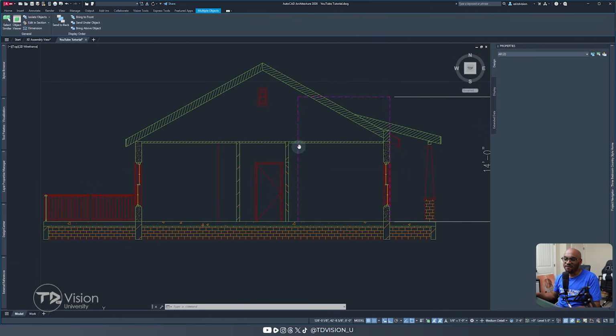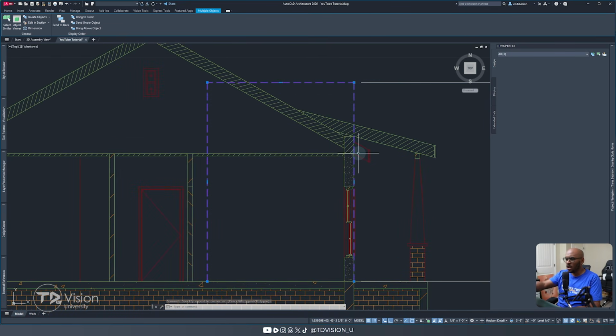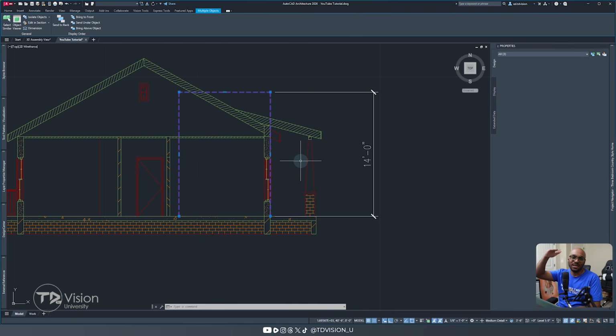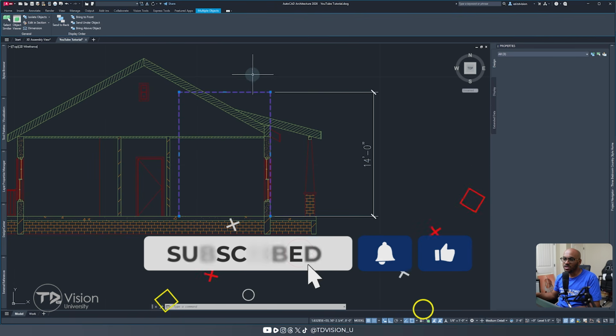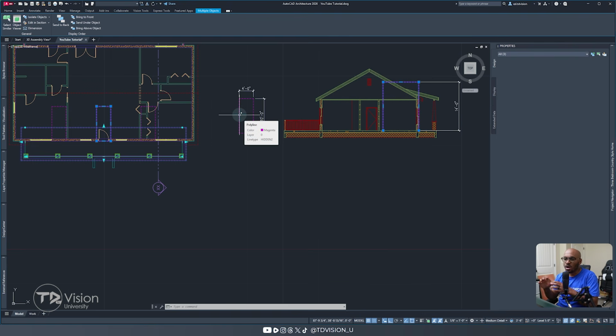Now, from an elevation point of view, this is what I'm looking at. So you think about how tall you want that wall to be for it to run into the roof on this side. And so we're going to be working with a 14 feet wall plate height for that wall, and then we're going to put the roof on top of that, which should end up somewhere out here. So what I like to do is to draw my dormer outside of the building first, and then I move it into the building.